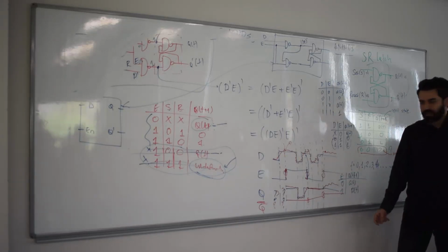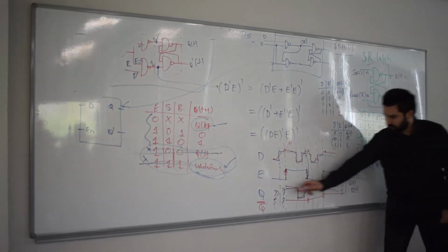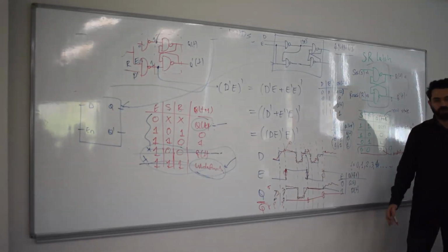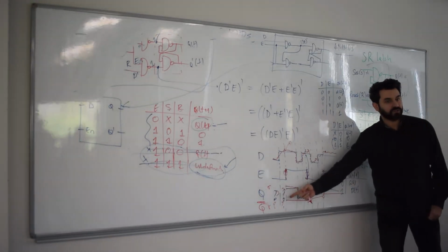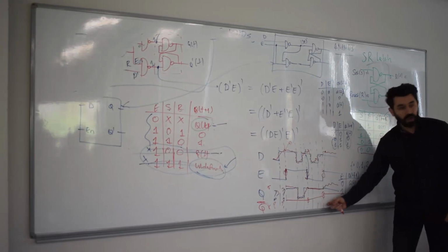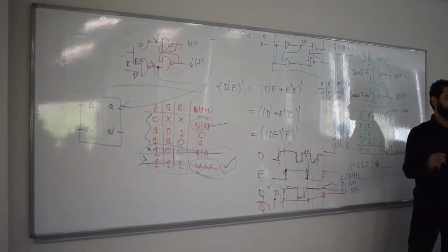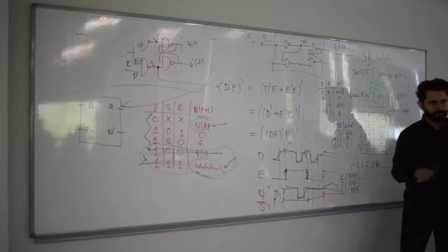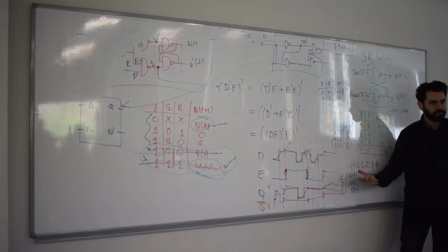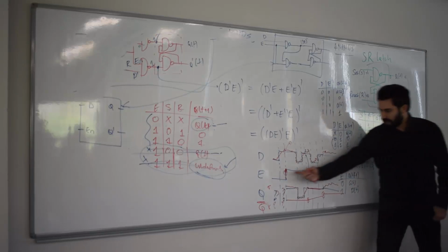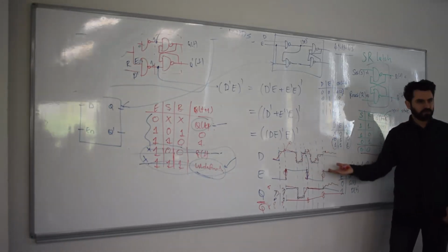in your state, but what I'm trying to point out is that when you look at these waveforms, the top one and the bottom one, you realize that there's going to be a lot of noise in the top one, which was the latch implementation. This one would be the flip-flop implementation, and this would have less noise. Of course, here the results do not look alike. The reason is this enable and D, there is no synchronicity between them. They are asynchronous, as you can see.